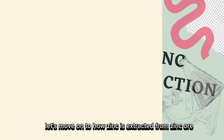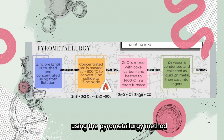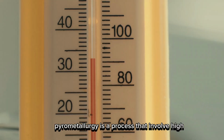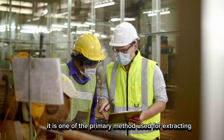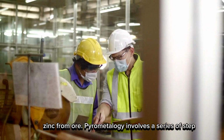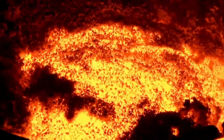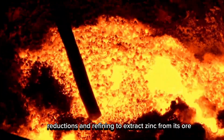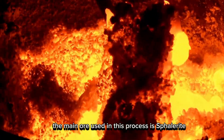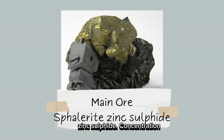Let's move on to how zinc is extracted from its ore using the pyrometallurgy method. Pyrometallurgy is a process that involves high-temperature techniques to extract and purify metal. It is one of the primary methods used for extracting zinc from its ore. Pyrometallurgy involves a series of steps including concentration, roasting, reduction, and refining to extract zinc from its ore. The main ore used in this process is sphalerite, zinc sulfide.